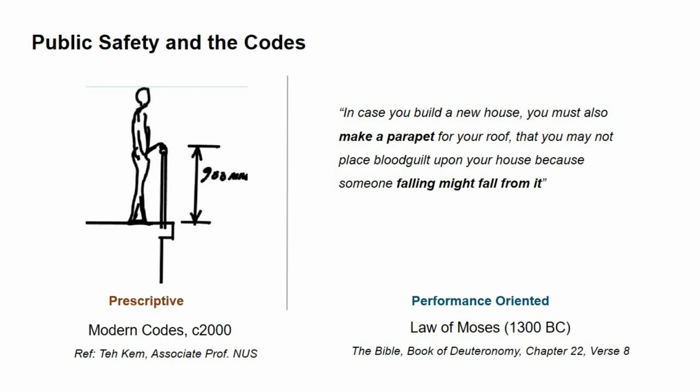Another example I want to give you here is, for example, modern building codes would provide you different safety factors or the minimum dimensions of different structural elements. For example, in case of a parapet, you can find that minimum height can be this much. But why building codes prescribe those minimum heights is to ensure a minimum level of performance which is intended from those components. Instead of using implicit performance objectives, prescribing different numbers or safety factors or some other empirical approaches, if your ultimate goal is to ensure performance, then the approach will be performance based design approach.